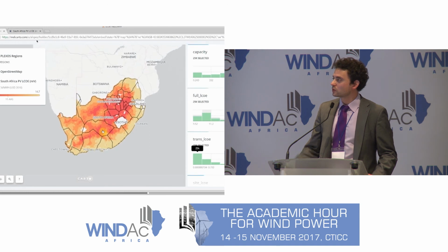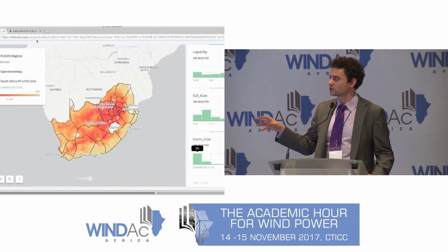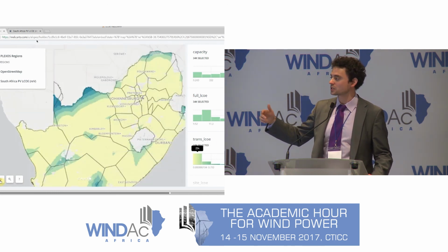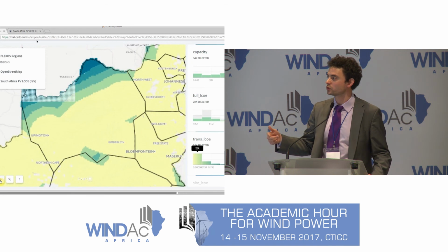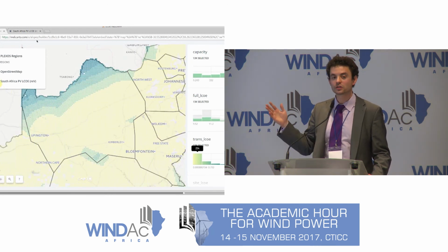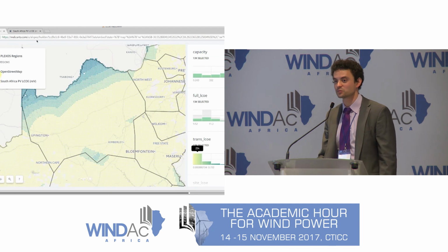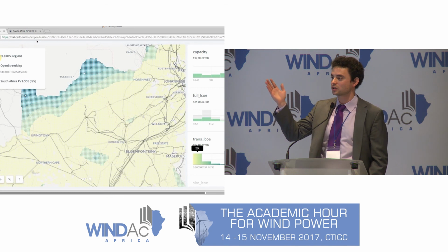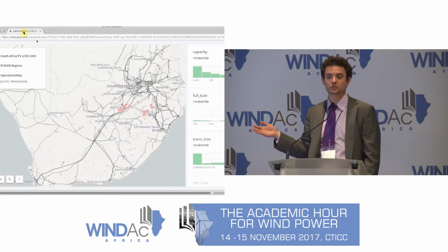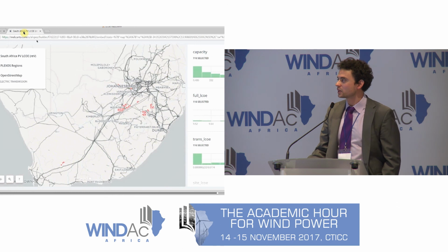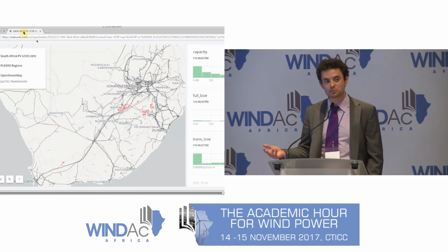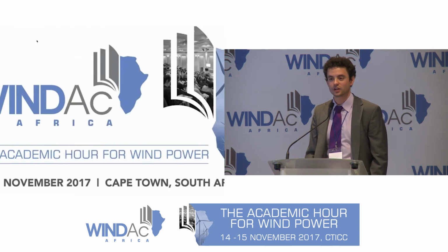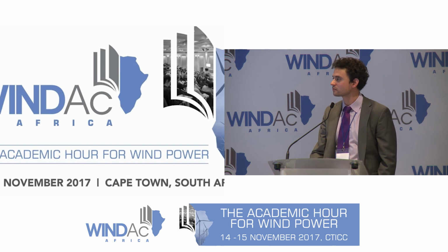And how this is going to change when we add these profiles into Plexos currently is we've added the transmission LCOE too. So if we look at the color scheme of that and then we superimpose just some open source transmission, although this was worked out with Plexos transmission, for visualization we superimpose some open source transmission, and you can see the further a farm is away from the transmission, the more it's going to cost to connect. And if we look at building the 30 gigawatts of cheapest LCOE for solar, it builds it very near the transmission and also in the best resource.